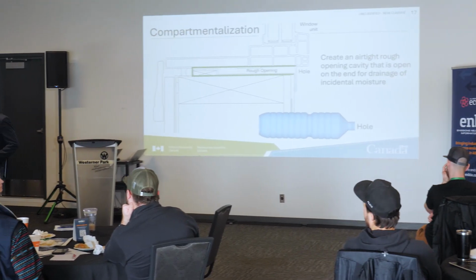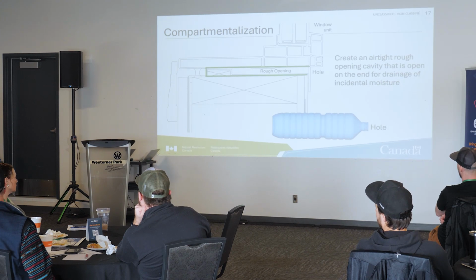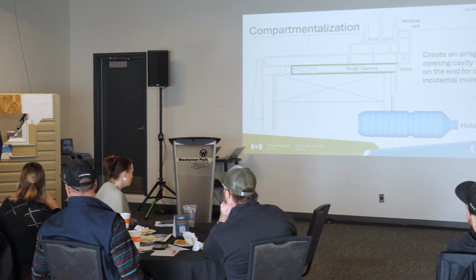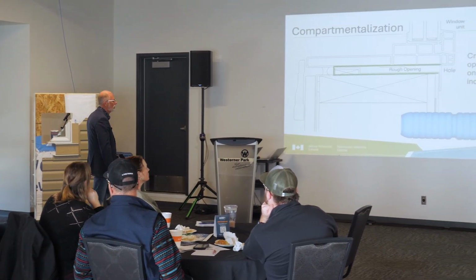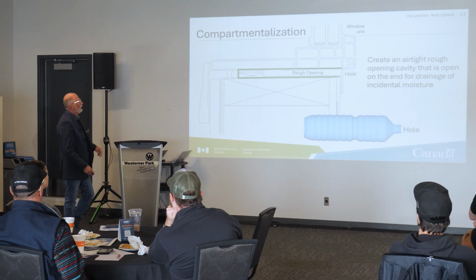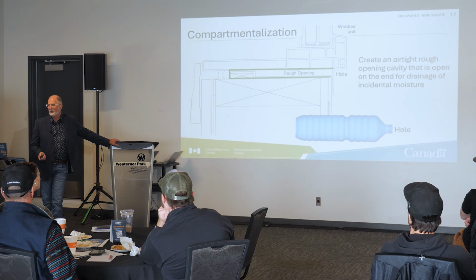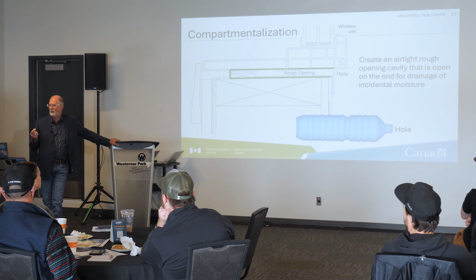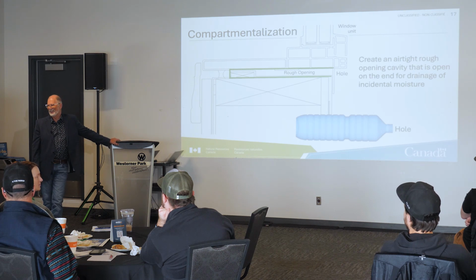In this model, the dam's further back, not at the jamb extension. Right, because most times the seal on the jamb extension is like a piece of tape. Yep. Are you worried long-term with that just failing and being wide open then? Well, I am, but it depends on the tape you're using, right? What's the compression? What just comes from the manufacturer? I know. It's like a thin piece of crap. Yeah. That's one way to look at it.